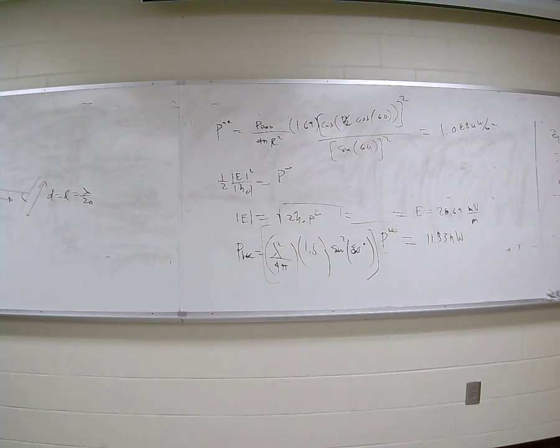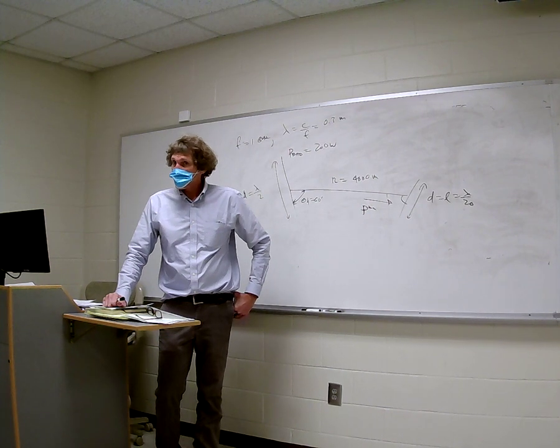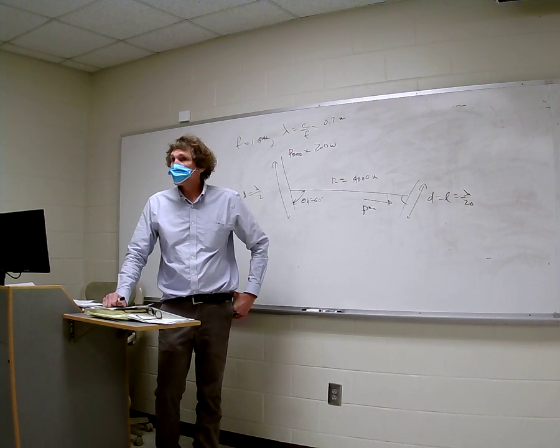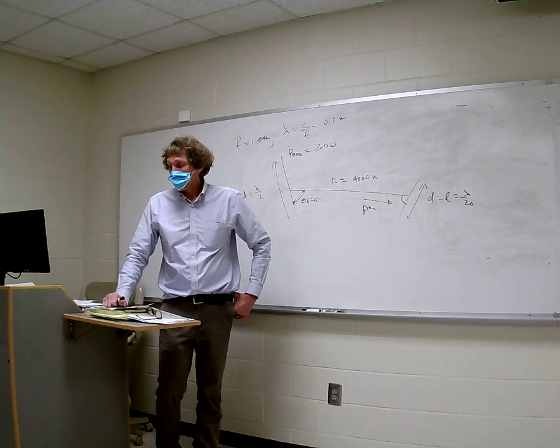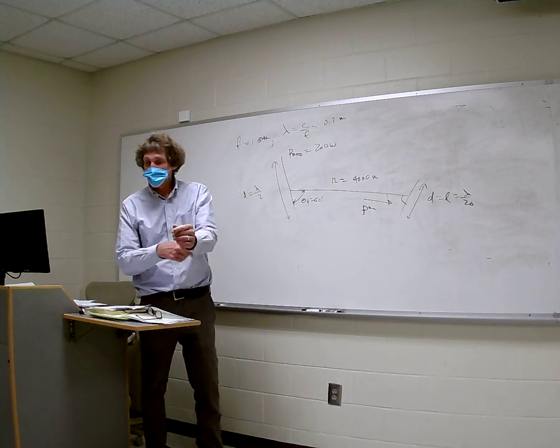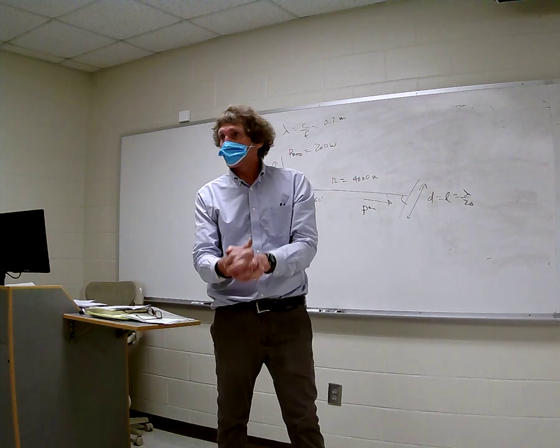The one point you should have taken from this is that for transmitting 200 watts, you get almost nothing out of that. You're down at 10 to the minus 8 watts out. Now that's because it's a low gain antenna, both in the transmitter and receiver. If you have high gain, you can get out probably 2 or 3% of the total transmitted power, maybe more. Okay, and we'll get to that later. I ran you over, I'm sorry. Any questions? If you need to go, go.